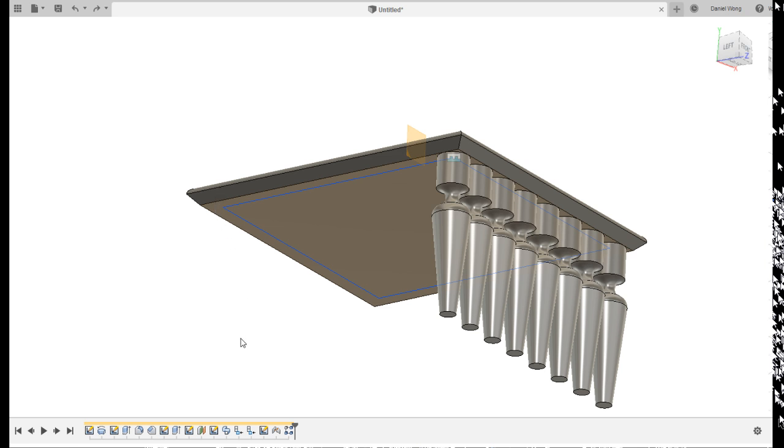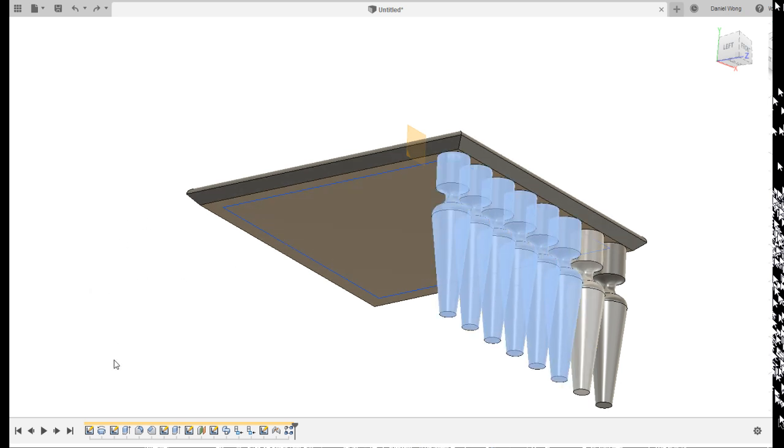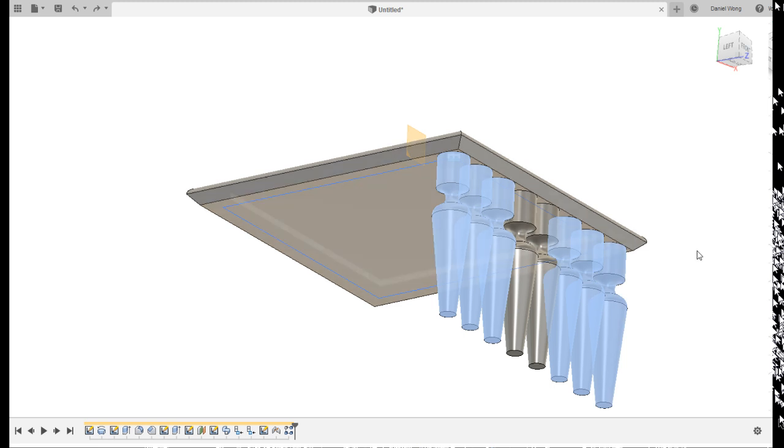and now you can imagine just mirroring it. You can mirror it across the other side, or we can use a rectangular pattern. So my objects in this case are going to be 1, and then 2, 3, 4, 5, 6, 7, 8. Actually, because I'm feeling interesting, I'm going to leave out 4 and 5. And we're going to leave a quantity of 2 and a direction of 84 in this direction here.